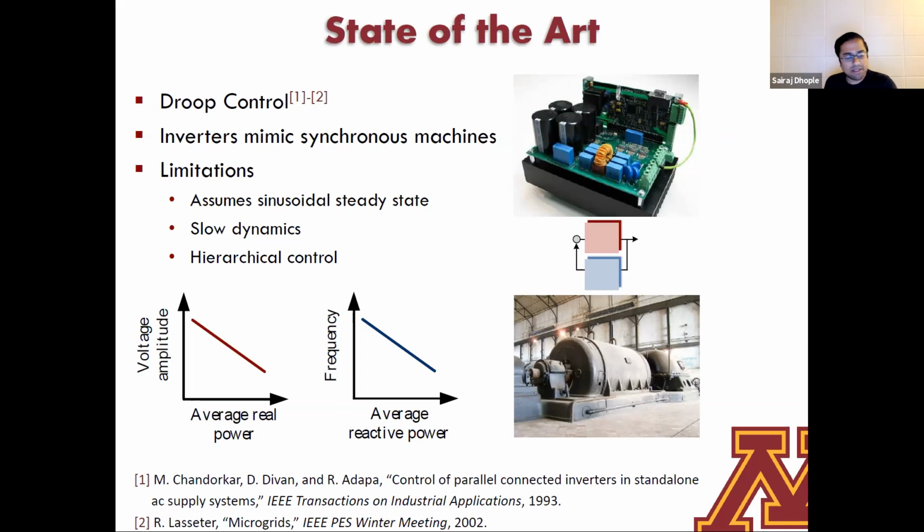And really the inspiration that they got here was to look at synchronous machines, right? They said, hey, look, synchronous machines, when you run them in parallel, they work. They can support loads. So why don't we just take that operation and try to mimic that in some sense over on inverter-based generation. So what it does then is it looks at the terminal behavior of power converters, and it imposes linear trade-offs.